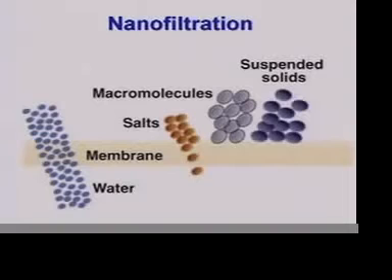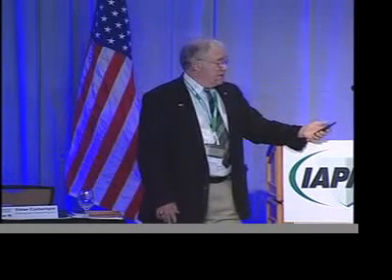You might say, well, what's the sense of doing that? Well, the fact is it uses less energy, is a less expensive process than reverse osmosis. If you're treating municipal water for a drinking water supply, in most cases, unless it's a seawater application, you don't really need the rejection capabilities of RO, but you can soften it with NF, nanofiltration.